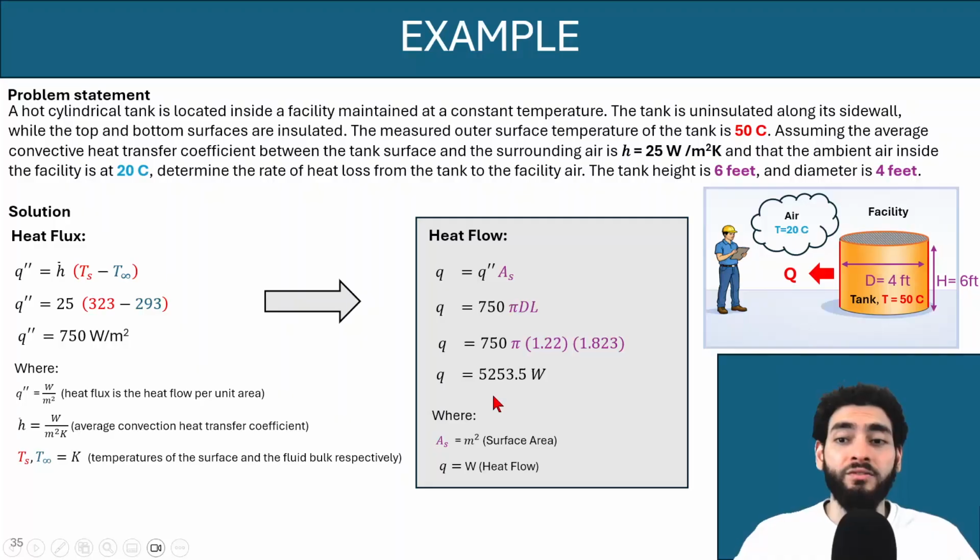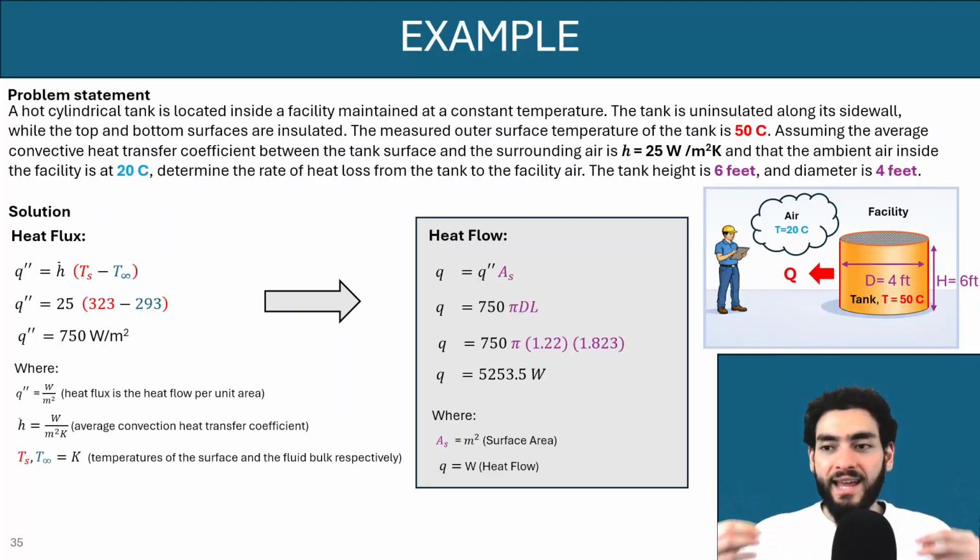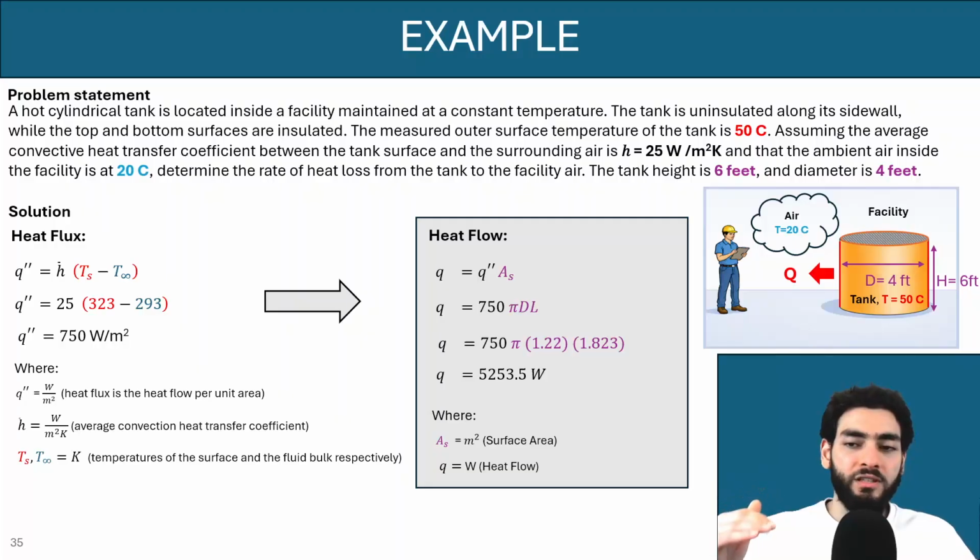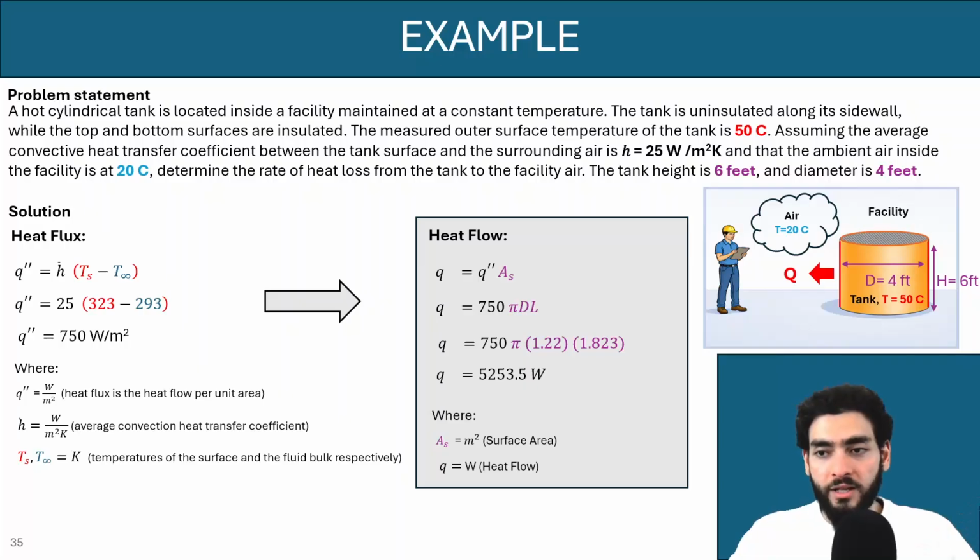Now, that's a lot of heat that the tank is dissipating to the outside. Usually that is something that would be very costly, because if you want to maintain the temperature of the tank, you probably need to add heaters. Otherwise, the heat of the tank will dissipate very quickly, and that temperature will not stay at 50 degrees Celsius. And in order to do that, you would need at least a heater inside the tank that would counter the heat loss of the tank to the environment.